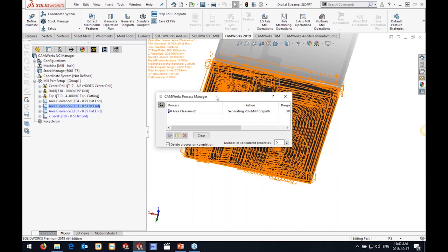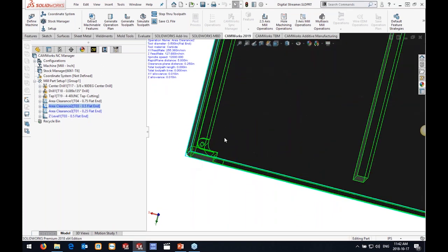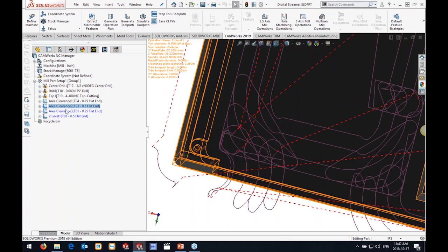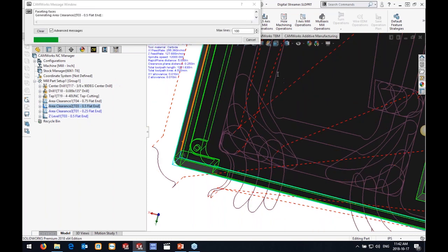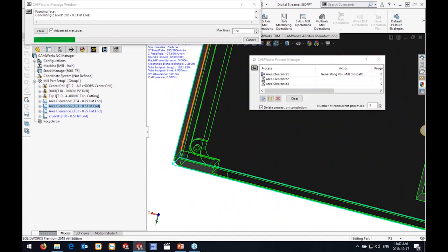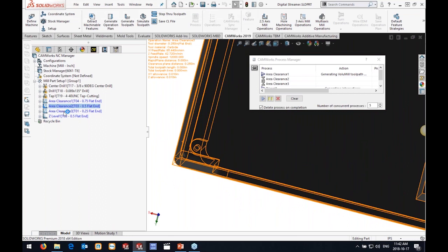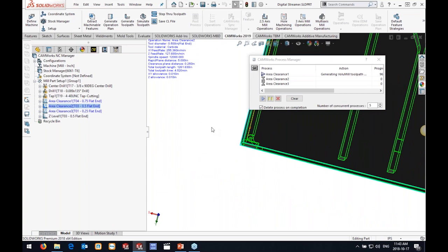So in this case, my 3/4 inch couldn't get into the corner right down here. It's a bit too small. And it's actually machining all of that leftover because I didn't generate the full toolpath. But then I'm going in again and machining the tiny little portions out with a 1/4 inch tool, basically to get my material out of the stuff down here. So you can now implement rest machining on volume mill in 3-axis. So now it's going to go through and generate those.